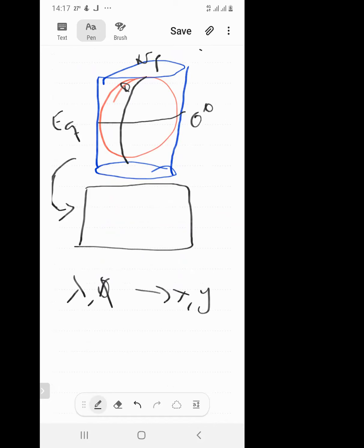Like I said, this is being done by software. You press a button, you tell it I want to move to this one, and it uses the formula that I showed you. Now you have your data on a flat surface, not on curved lines, because the longitude and latitude are kept. As they go to the top, two lines that are parallel shouldn't meet, but you see that they are meeting up here. And that's where the challenge is. So this is the cylindrical projection, another class of projection.